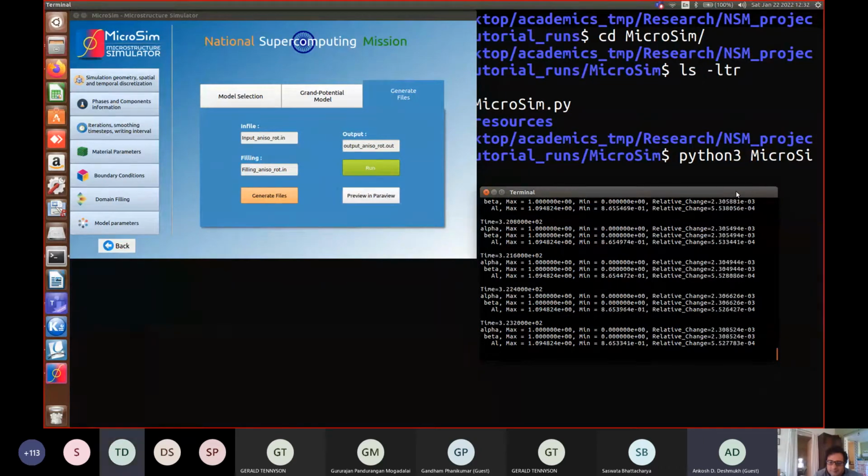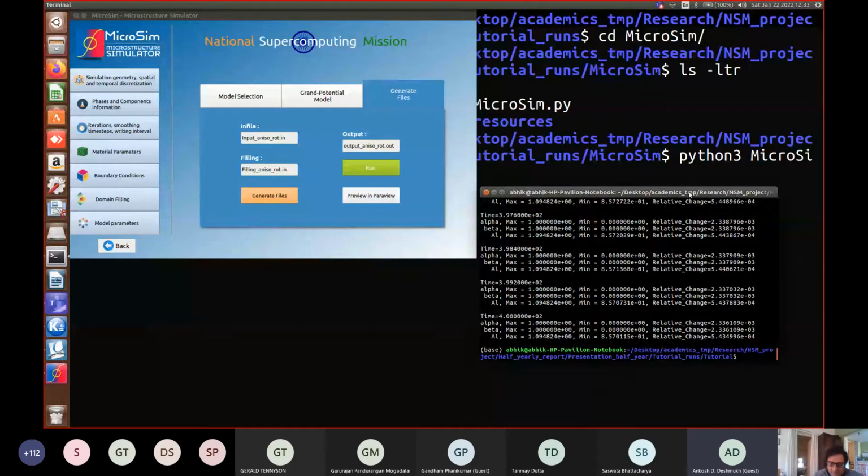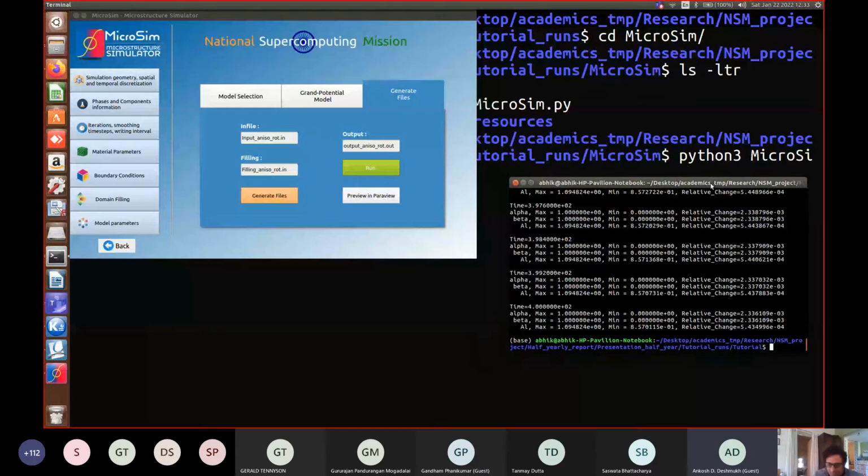There is one question from Harris Daniel in the chat. How are you coming up with non-dimensional model parameters? Okay, so non-dimensionalization is the user's headache. If you put in non-dimensionalized parameters, the code will run with non-dimensionalized parameters. If you put in dimensional parameters, everything will run with dimensional. So the infile does not know any non-dimensionality.